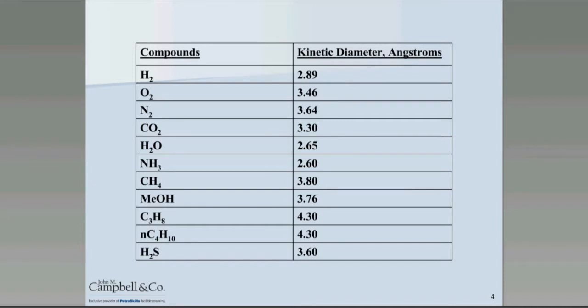Molecular sieves have very precise pore openings. For a molecule to be adsorbed on a molecular sieve, it must be smaller than the opening into its pores. In a type 4A molecular sieve, any molecule smaller than 4 angstroms can enter the pores. Type 4A sieves are used in most dehydrators, so components smaller than 4A will be adsorbed. In addition, if the molecule fits into the pores, if it's strongly polar, it will be held onto the surface of the molecular sieve much stronger than any nonpolar molecules.